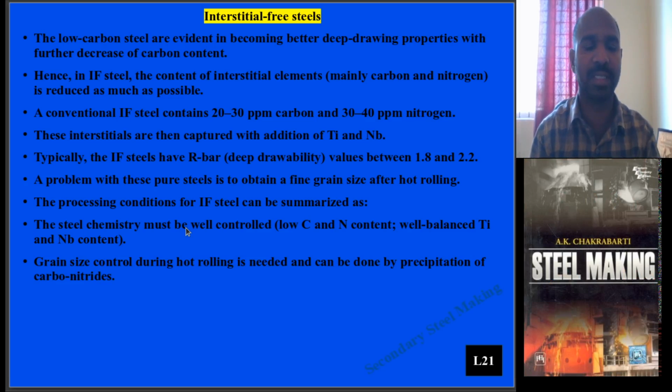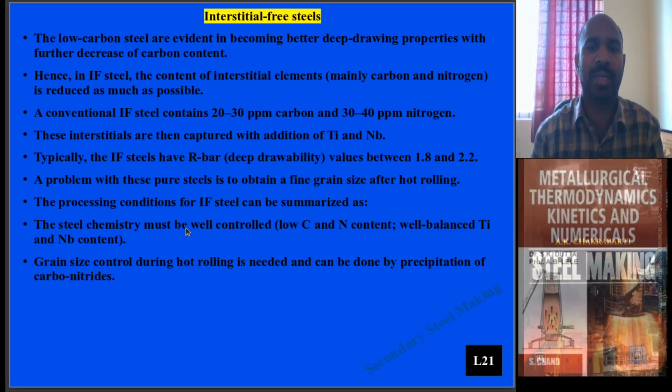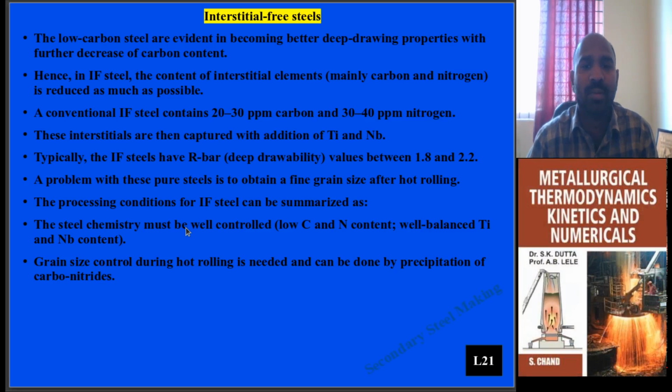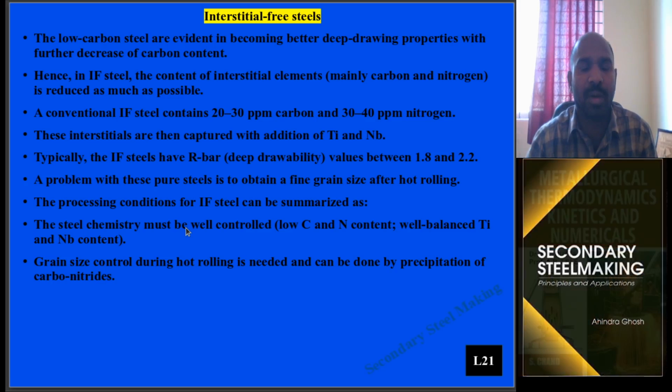The grain size can be controlled by the addition of titanium and niobium, allowing the formation of precipitates such as titanium carbide and titanium nitride, and likewise with niobium.